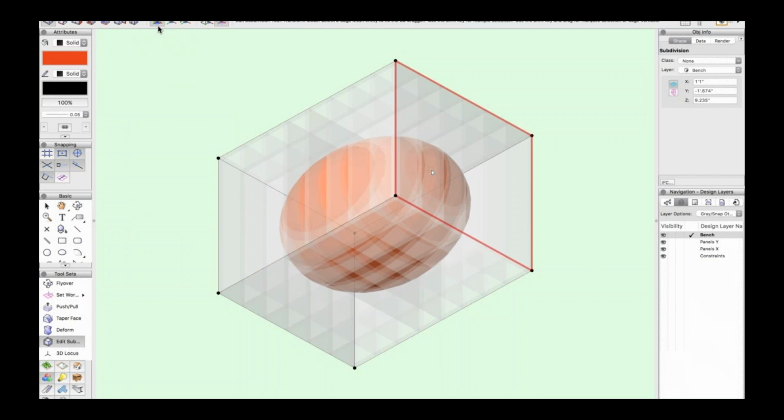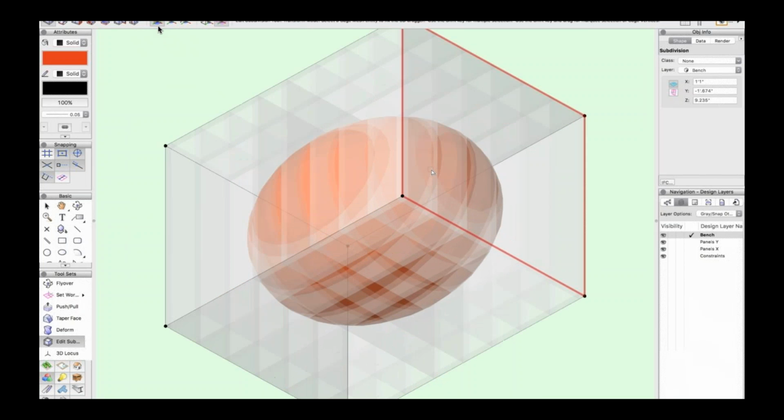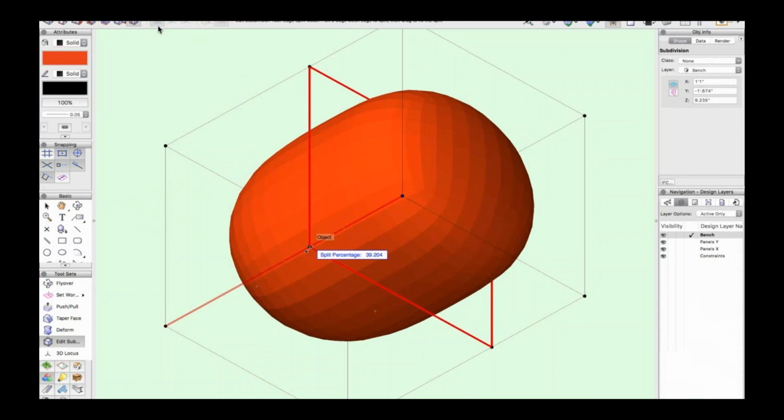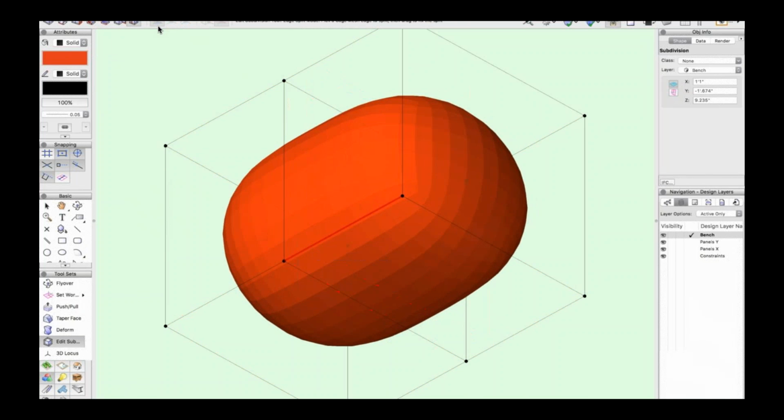Well, you may have noticed the arc, and we'll see the 3D dragger again here in a moment, but the arcs connecting those axes, that essentially gives you the ability to rotate the face, edge, or point by clicking on that arc and dragging it from left to right, or using the tab key to enter an exact angle as you prefer.